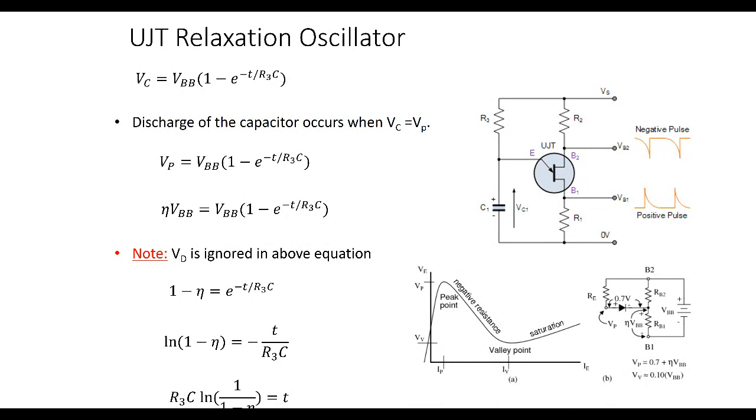What I would do is we have a source voltage. I would, based on the circuit, if I want the resistance there, I would say it's the source voltage minus the VP, and since the peak is at IP, I would divide it by IP.